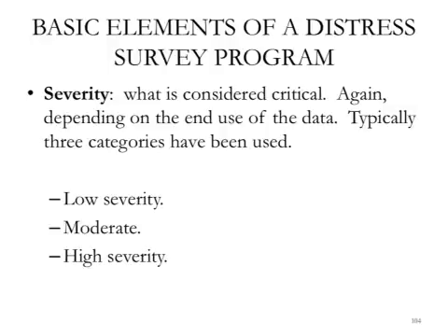Typically there are three categories used so far: low severity, moderate severity, and high severity. Some agencies would just say low and high. Some other agencies, if they are dealing with very sophisticated types of distress, may even come up with a fourth or even a fifth degree of severity. So it depends, but typically the rule of thumb is low, moderate, and high severity.